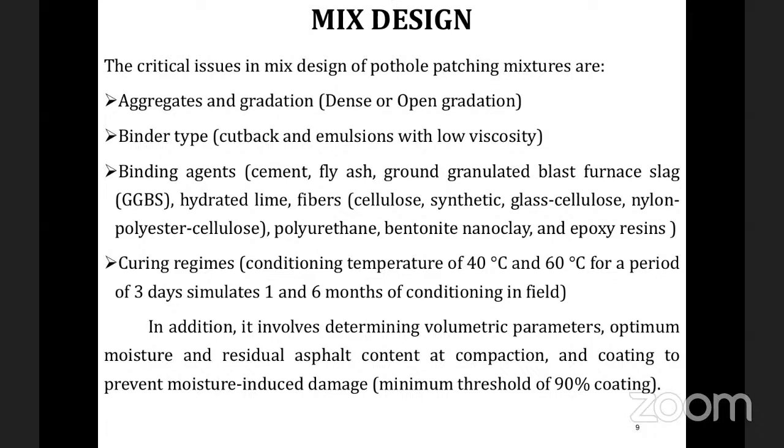In potholes, the next aspect is the curing regime. Once we prepare the mix, we have to cure it, because it is a cold mix. As we know, based on the review of the mixes, a conditioning temperature of 40 to 60 degrees Celsius for a 3-day period can be used.